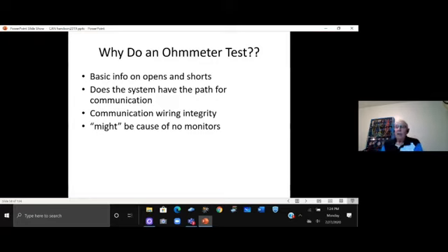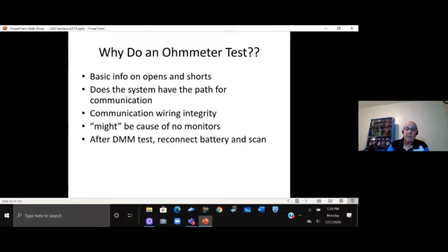We find if you've got 120 ohms, does the car still run? Yeah, most of the time. Does it run well? Yeah, probably. Would the customer even know it? Maybe not. But now he goes through his emission test, he plugs in, and that's when they realize, hey, none of the monitors have run. Sorry, go get the monitors to run and bring it back. It's either going to be a reject in some states, or it's going to be a fail. So it's a very, very common cause of no monitors.